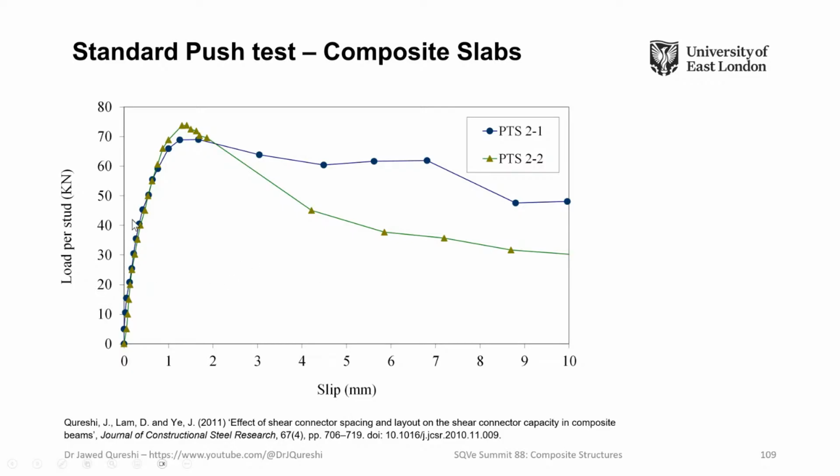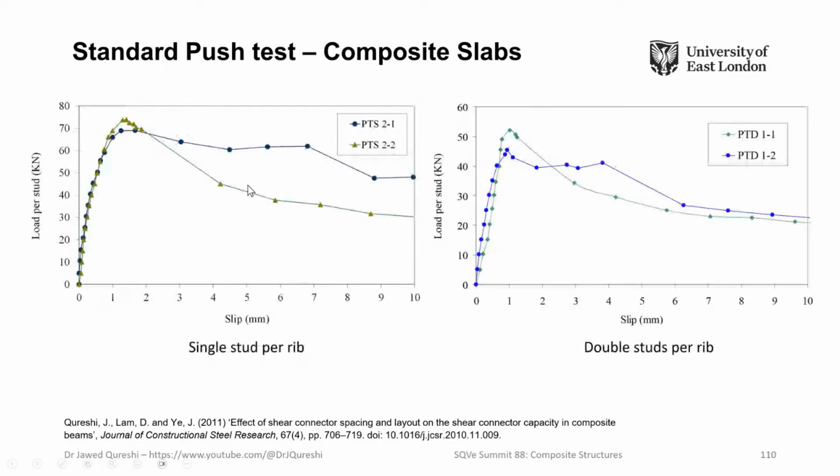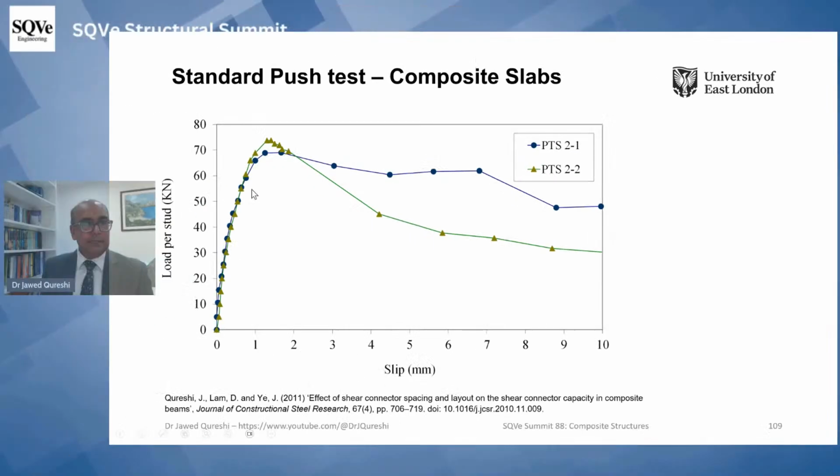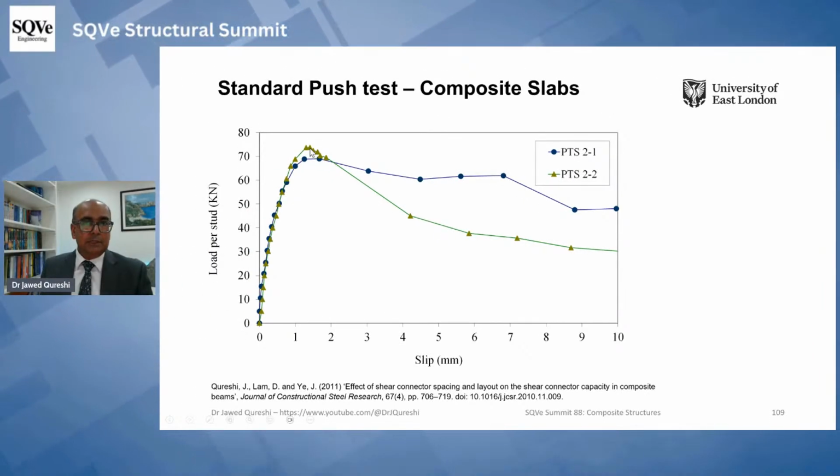Now this is how we got shear stud strength, and you can see here that the stud strength is about 70%. In design codes, they carry out lots of testing, figure out what the shear stud strength is, and apply partial factors, and after applying partial factors, it comes out to be about 55 something. So that's how they do it in design codes.